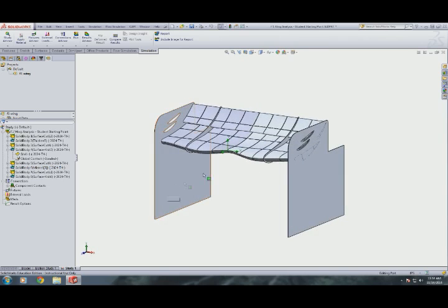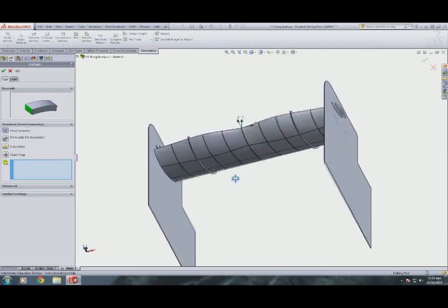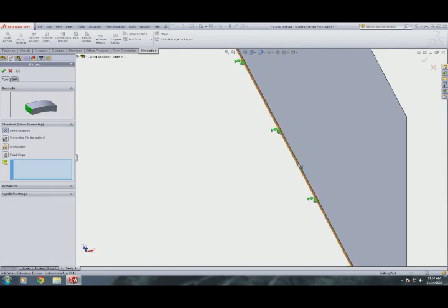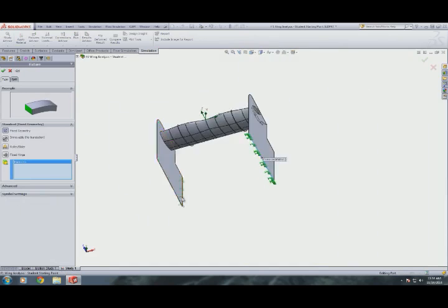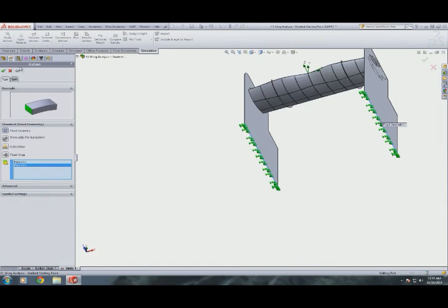We can go ahead and establish next which parts are fixed, which, I mean, we want to do fixed geometry, and in this case, you'd normally get the bottom of your wing here fixed to the car, which is exactly what it is in our scenario. So fix those bottom surfaces. They won't rotate, they won't move.